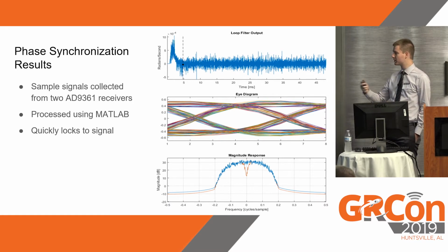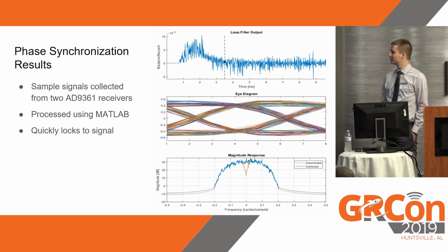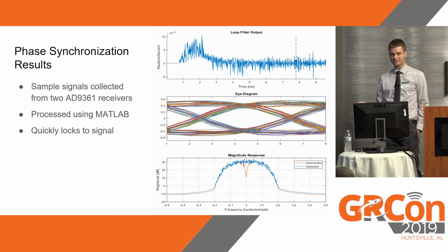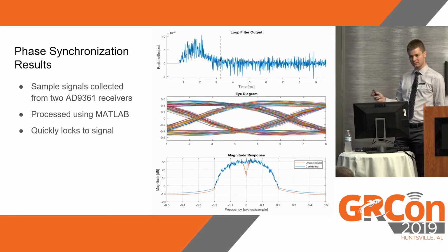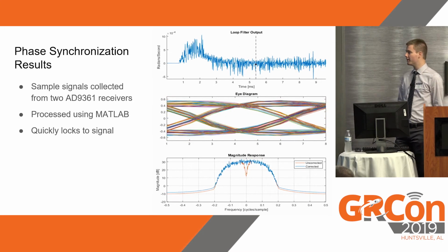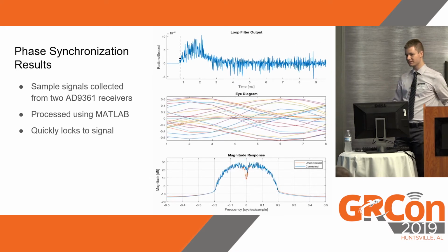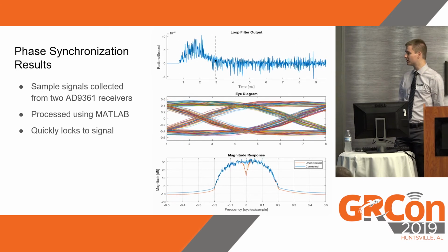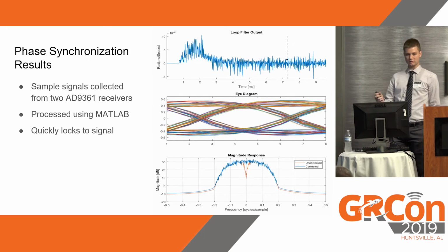We implemented the whole algorithm, simulated it in MATLAB. And you can see here, when we start out, it very quickly, within a couple milliseconds, locks onto the signal. You can see it, initially the eye diagram is just a complete mess, but it very quickly sorts out those phases so that the signals are added coherently. And you can see that also in the bottom here, where the orange signal is the combined signal using no feedback.